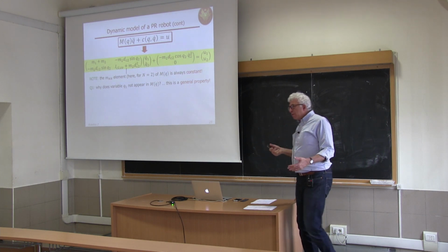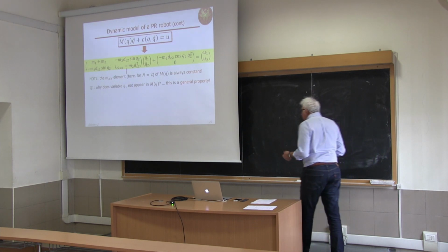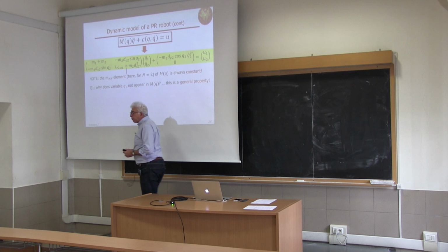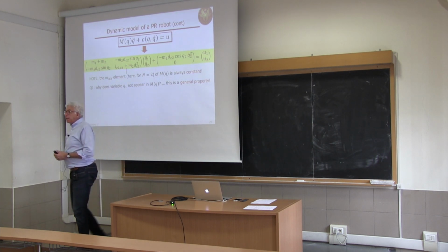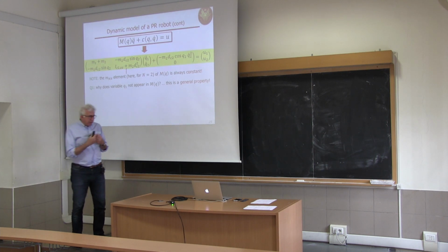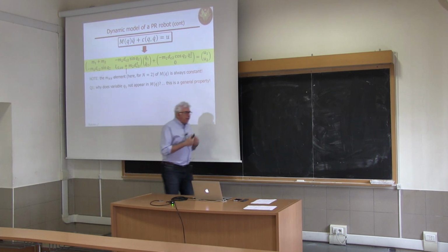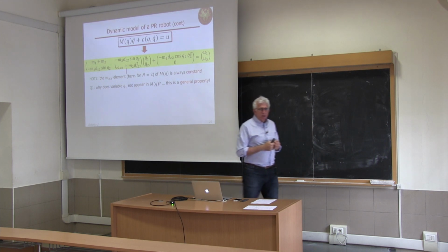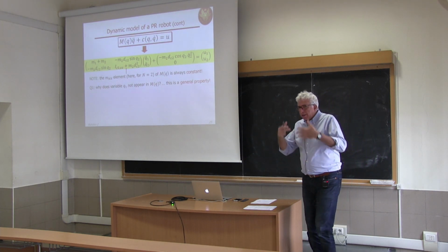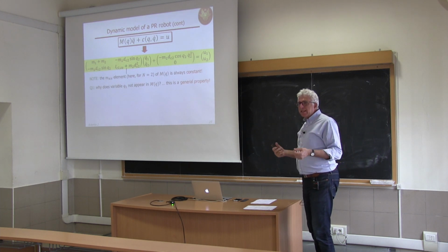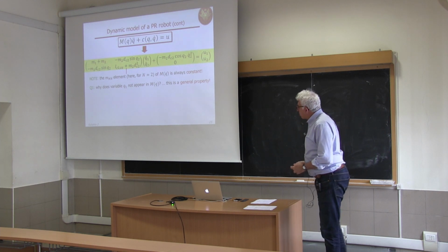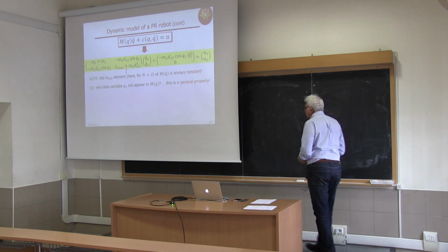If you think about it, this variable can in fact assume any value depending on how you choose frame 0. And this is why a physically intrinsic property like the inertia of the structure cannot depend on this variable. Because you would have a larger or smaller inertia, in an intuitive sense, depending on how you choose the base frame. And this is not physically consistent.